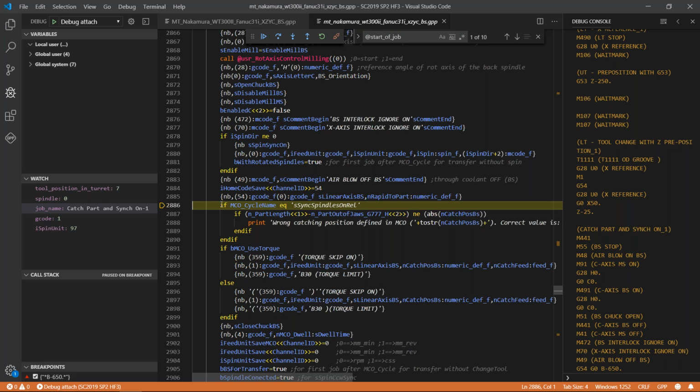As an experienced post-processor developer, you can fully ask why it actually stopped here. I don't see anything here. Now, the very important thing is that it will never stop in the same line where it is printed. We are actually stopping it after that block, so the line before. We must first print it out, and then we analyze what is inside that line, and we will always stop in the line after. Okay, so this is very important.